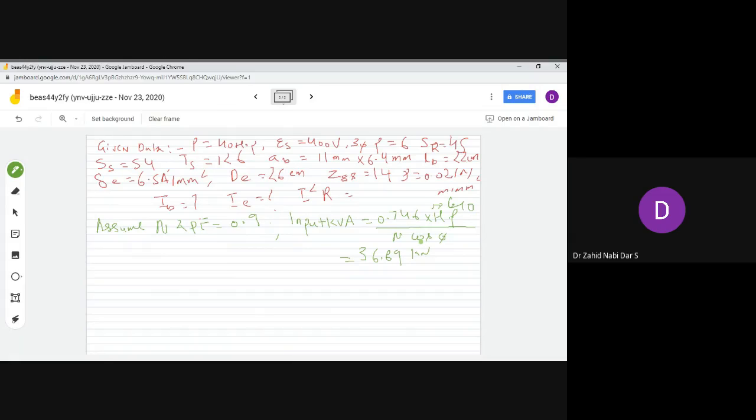Usually what happens is here there is no mention of any connection. This is a very typical question, that's why I have taken this. Now the voltage level is giving you 440 volts. Now you tell me one thing. Usually we always connect the stator in delta fashion, so the stator is given delta fashion, not the star fashion. Why is it done? Why is the induction motor started with delta?